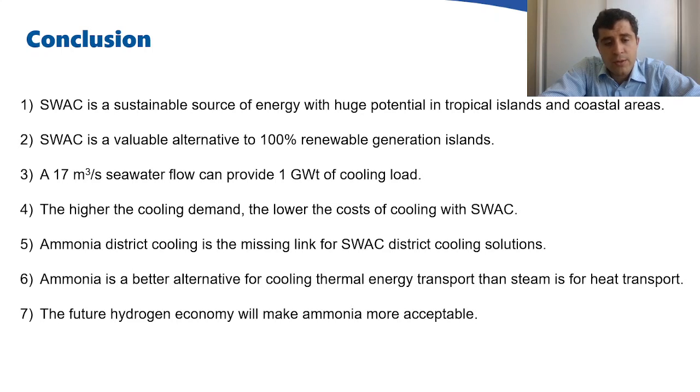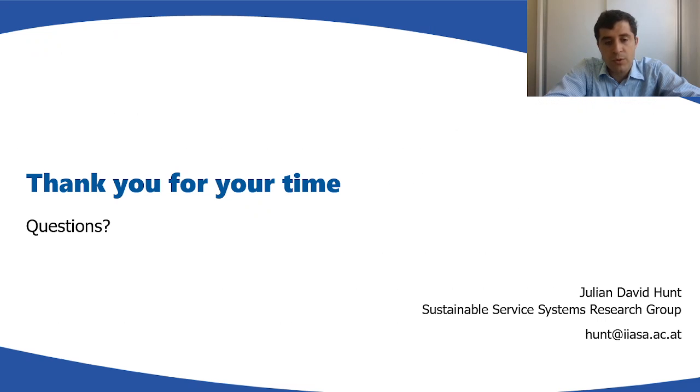The higher the cooling demand, the lower the cost for cooling with SWAC. Ammonia district cooling is a missing link for SWAC district cooling solutions. Ammonia is a better alternative for cooling thermal energy transportation than steam. And the future hydrogen economy will make ammonia more acceptable and will reduce the risks of using ammonia.